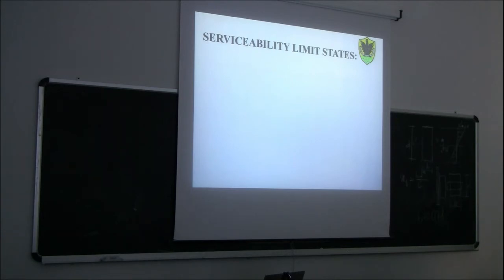Okay, which are the other verifications? Shear at the supports. Okay, so bearing, so compression perpendicular to the grain over the supports. And buckling, lateral torsional buckling of the beam. So we have 3 ultimate limit state checks and let's say 2 serviceability checks.